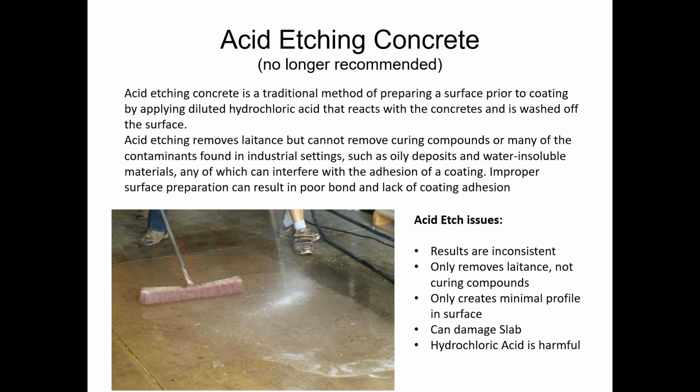So as soon as you put it on, it will react, but it neutralizes itself because there's so much lime or alkalinity on that floor, so it stops working. The other one is you've just finally got the floor dry enough to paint, and now you're wetting the living heck out of it again before you paint it. So it sort of defeats the purpose, and it's a mess and everything else. So we don't like using acid etching. It's not as efficient as what you think and causes all sorts of other problems, which, to be honest, are a bit boring and we won't go into today.